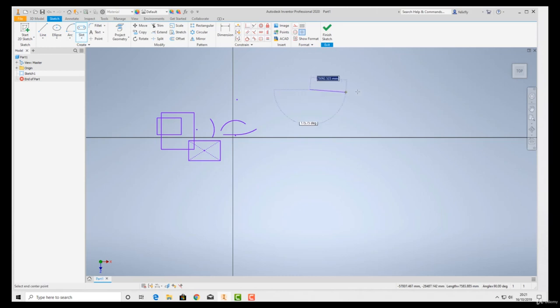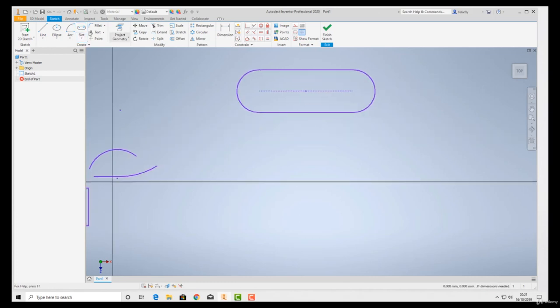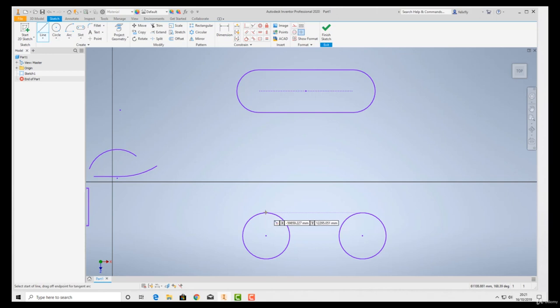First of all, you click your line and then you click your width. Now I'll show you what I used to do. I used to draw a circle. If I wanted to create that geometry, you draw a circle, draw another circle aligned to the midpoint, and then you can see the construction out, so it's the same width. And then you'd connect up the lines, you'd make sure they're tangential, and you'd trim it out.